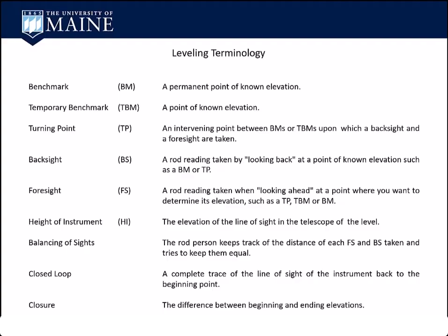Temporary benchmarks, it's a point of known elevation. It's just not something that has the permanence of a benchmark. It's not something that you put a lot of effort into establishing. So it just might be control on the site. It could be a rim on a manhole or top of a platform or a step, something like that.